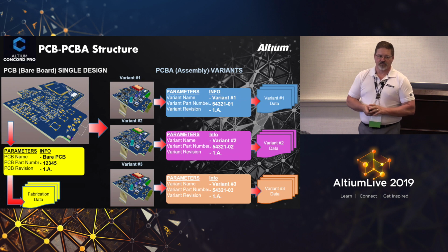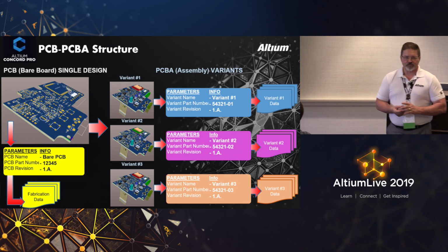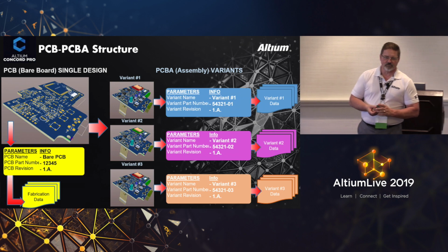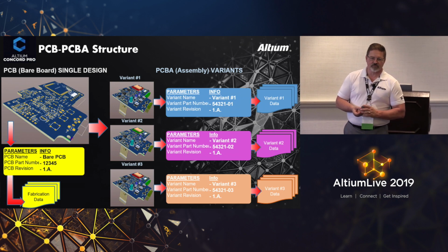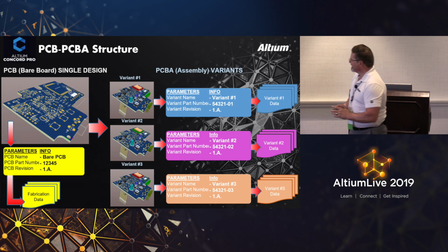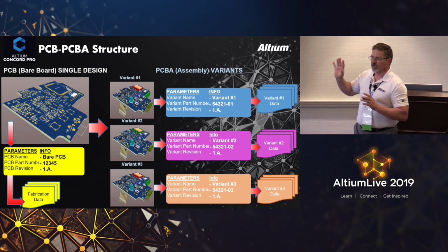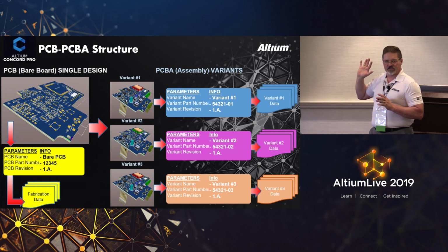I'm just looking at the design. There's our Altium design. The design package is basically our managed project, like we talked about. That basically has the revision itself, separate from all the outputs it generates. Right. So you've got to divide up your project in this way, where you have your PCB side and your PCBA side.